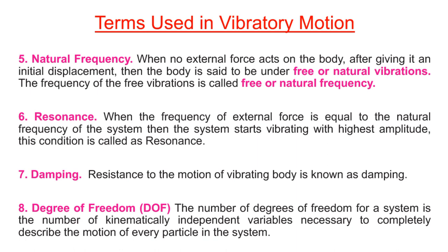In vibration it is most important to know the degree of freedom of the system, so that we can derive an equation based on these degrees of freedom and solve it to find the displacement, velocity or acceleration, that is, the amplitude terms of vibration.